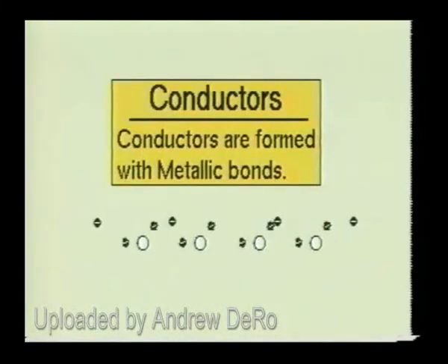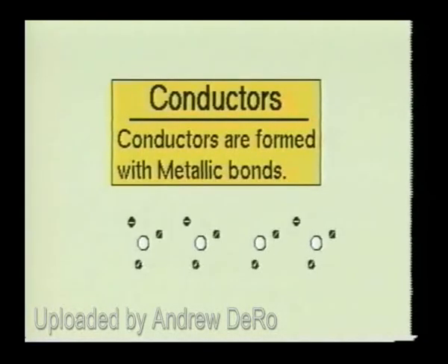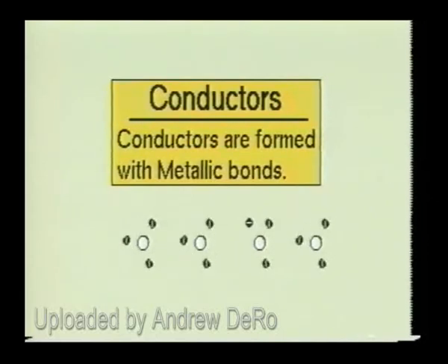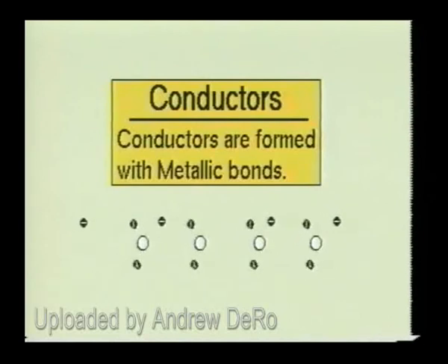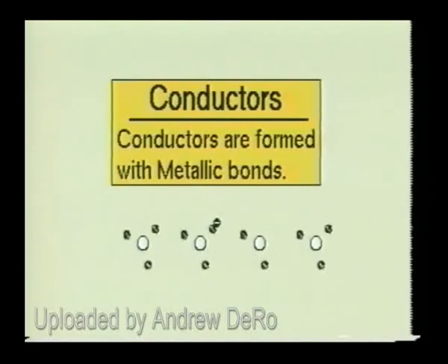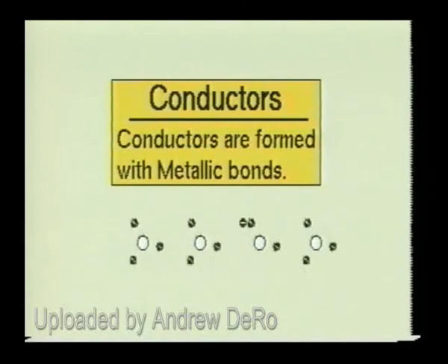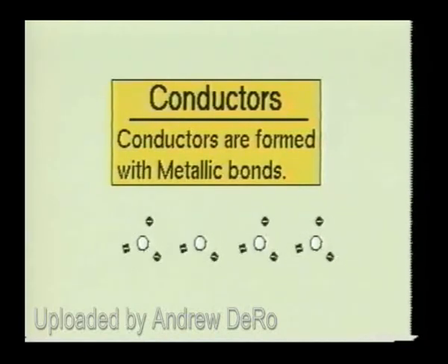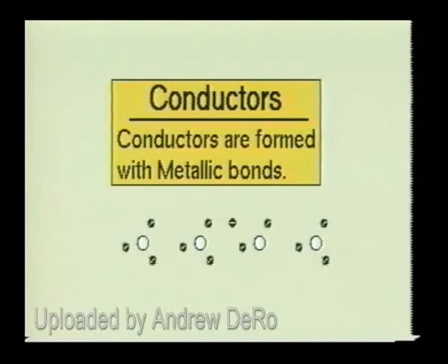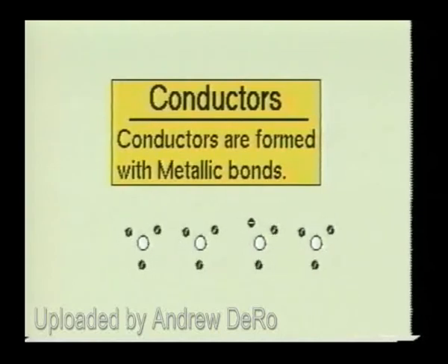Metallic bonding occurs in materials which are used for conductors. As you learned earlier, conductors contain a large number of electrons which are available for conduction. As the electrons leave the valence ring of the atoms within the material, the atoms become positively charged and therefore become positive ions. A strong electrostatic force will exist between each atom and the many free electrons. It is this strong electrostatic force between the atoms and free electrons which forms the actual bonding of the material.